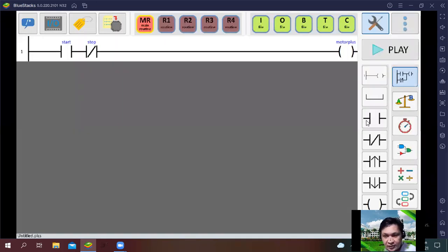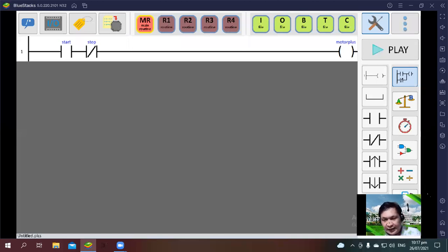Now, in certain circumstances, you can actually directly take the analog input from that particular pin. In our case, the analog pins that are available for use are limited to only two. I0.0 and I0.1 are not part of those.